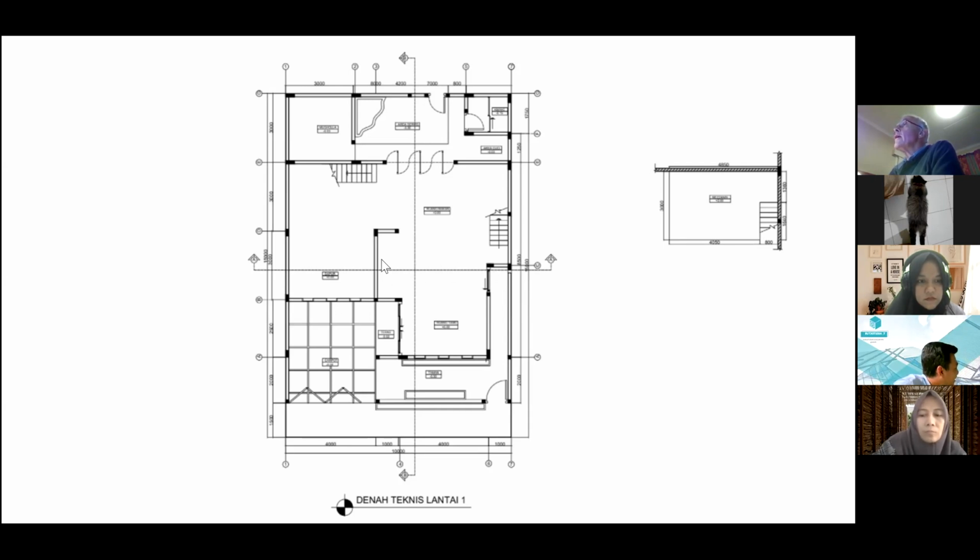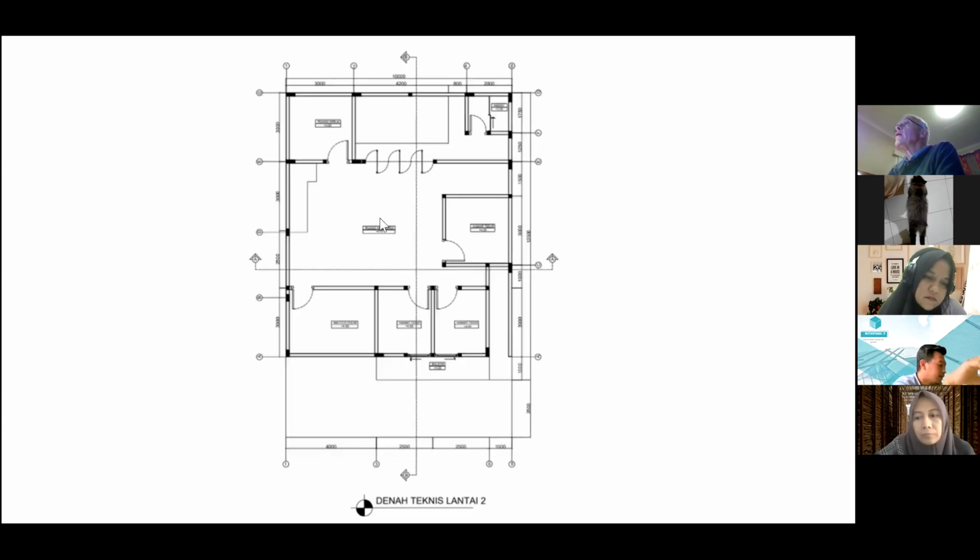What about grid line C? Well, we have a very short wall, but this wall is so skinny, it's going to be too weak and flexible to be any good to resist earthquake forces. So we can really neglect it. And the same with this wall, which is so short. And notice, it's on grid D in the middle of the plan. If we go to Lantai 2, there's no wall there. And so it's not useful to resist earthquake forces. There's no structure here.